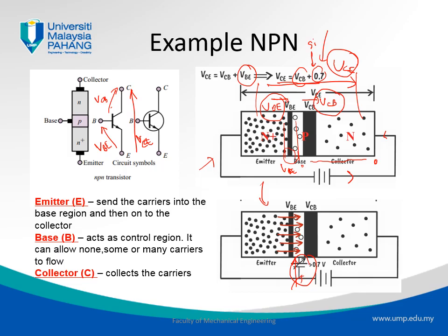If we get across the bias voltage of 0.7, it means we can cross this depletion layer. When the voltage applied to the base is at least 0.7 or larger, what happens now is that we can go across the depletion layer. And who wants to go across the depletion layer? The thing that wants to cross is basically the extra electrons that we have in the emitter. Emitter means we have N plus, it's highly doped, so these electrons want to go to the other side.